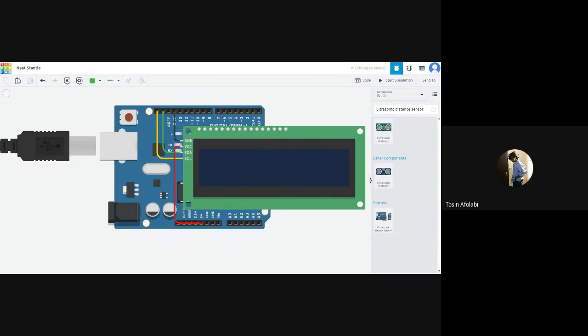I'm going to be very honest with you, I don't know exactly how this one works, because these are connected to this part, I don't know if it's part of the digital pins. I was rushing. The one I was trying to create: the SDA was going to go to A4, then the SCL to A5. I was going to connect it along with the ultrasonic sensor we used last week, to display the distance measured and other things like that.